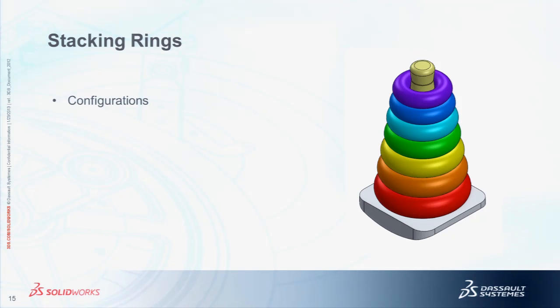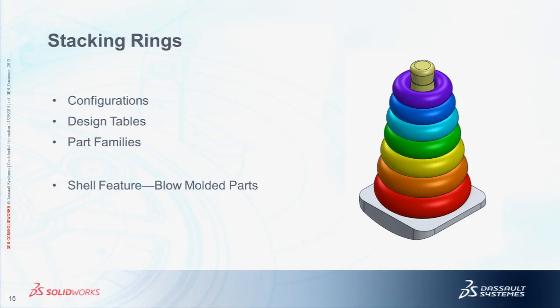You've got a part there which obviously has configurations that lends itself to a design table. So we've got basically a donut. You've got a couple of diameters there, and from there we can make a design table which reflects how each configuration changes, as well as the colors. So of course, obviously this ends up being a part family.